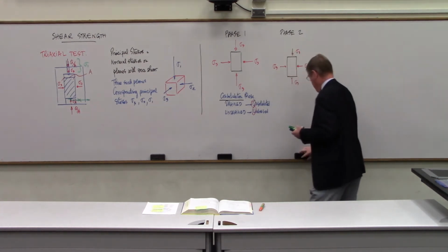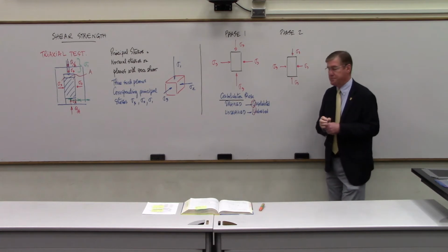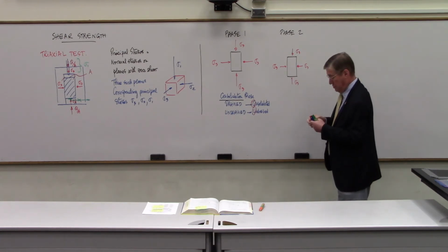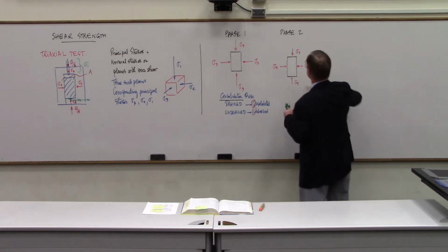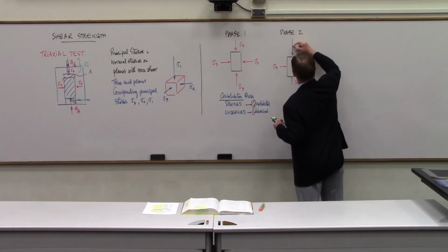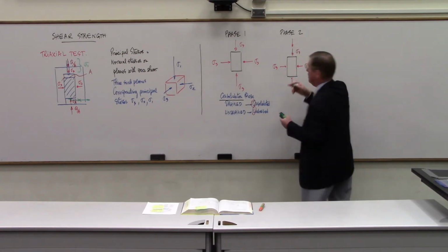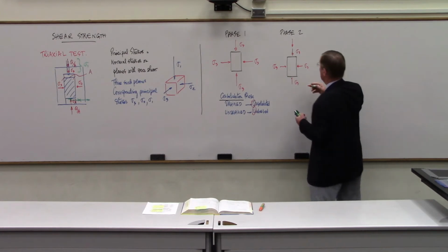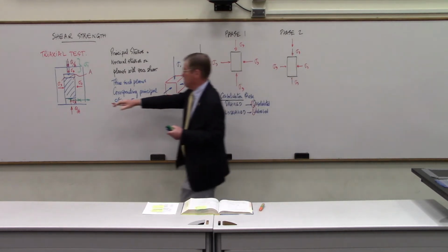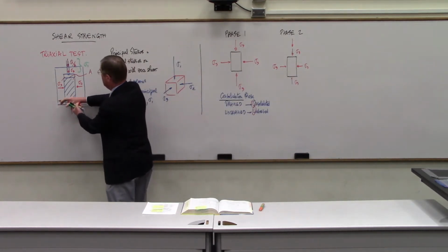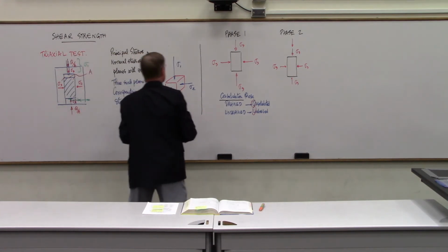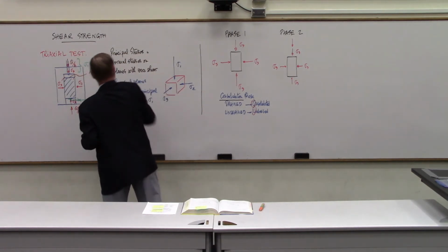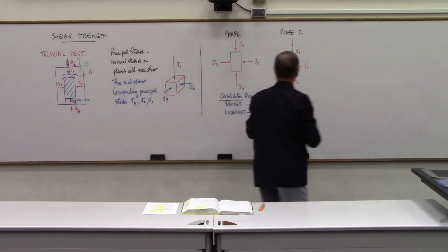And now we're going to shear the sample. And to shear the sample, we're going to increase the stress in the vertical direction by increasing the load. And we do that typically by taking the bottom platen here, and then we push up against a resistance here, and then we have a measuring device on top of the piston.